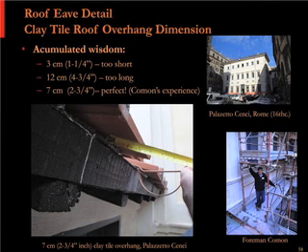That's thought through. And that's one thing I learned from Camone, who was the foreman on one of the buildings I was looking at, Palazzetto, the Little Palace, Cenci in Rome. This is actually the RISD program in Rome's building, and they were kind enough to let me on there. So he was the one that told me this, and this was pretty early on in the year when I was there. They were doing a roof restoration work. You see that at the left. And he said, yeah, when we overhang these tile, it's got to be 7 or 8 centimeters. That's about 2 3/4 inches.